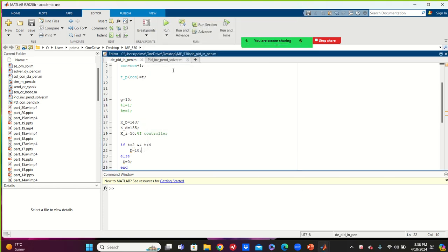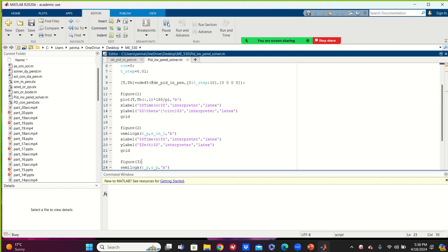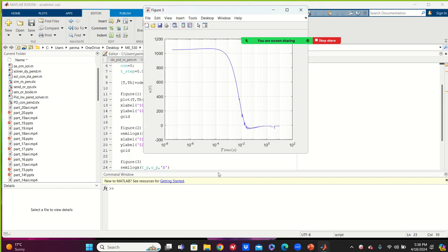Oh, okay. I'm going to show it to you. So you have to add a disturbance for the linear system here. Here, D. I just added D beside. Now I'm running that. Oh, you see the effect of that here? Disturbance. So the controller tries to overcome that.